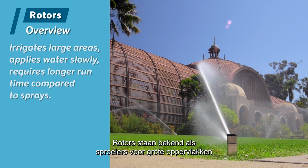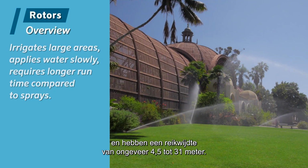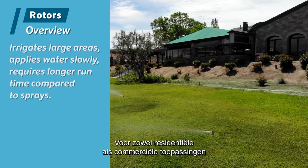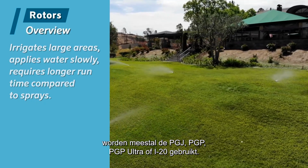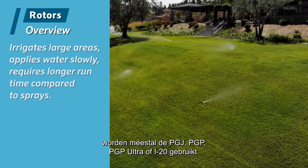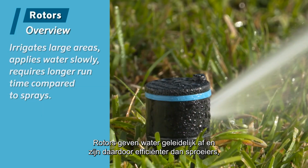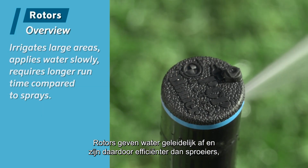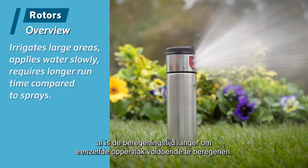Rotors are known to be a large area type sprinkler and have a radius range from 15 to 103 feet. You will typically use PGJ, PGP, PGP Ultra, or I-20 for these large areas in residential or commercial applications. Rotors apply water very slowly and tend to be considered more efficient than sprays, but will require longer run times to adequately irrigate a given area.